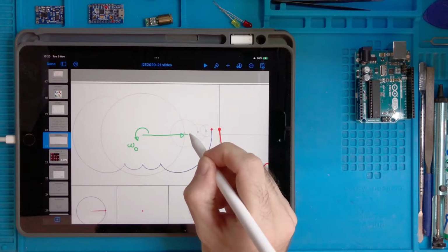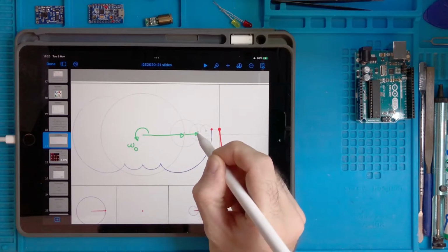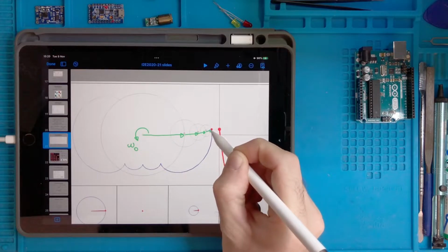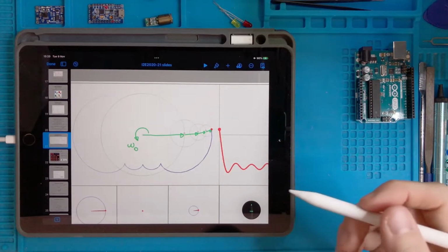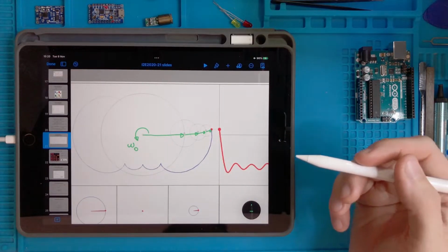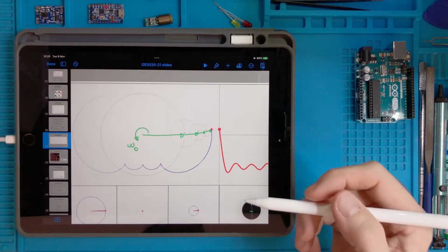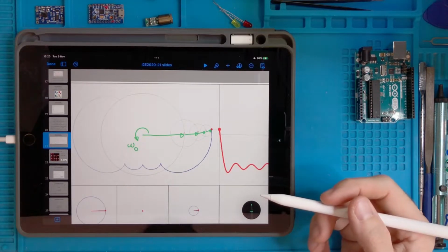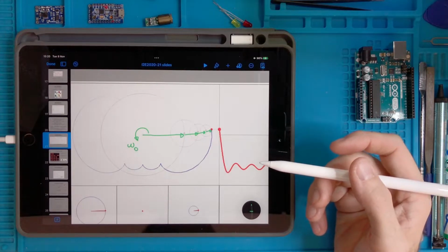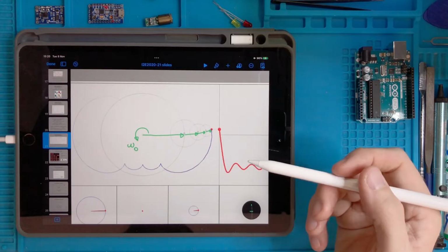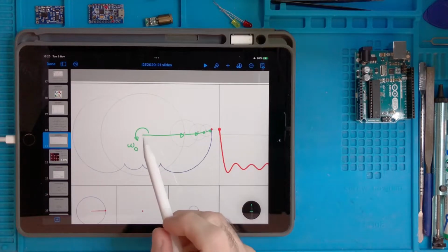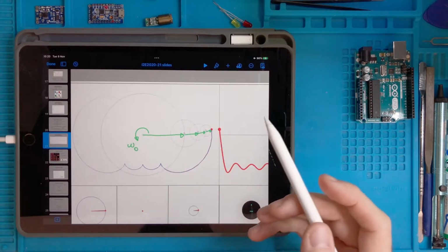Then there will be another phasor. We have to add another phasor, many phasors. Actually, there is an infinite number of phasors that we have to add in order to exactly reconstruct our signal of interest. But we don't do this now. We just consider the summation of the first 1, 2, 3, 4 phasors.